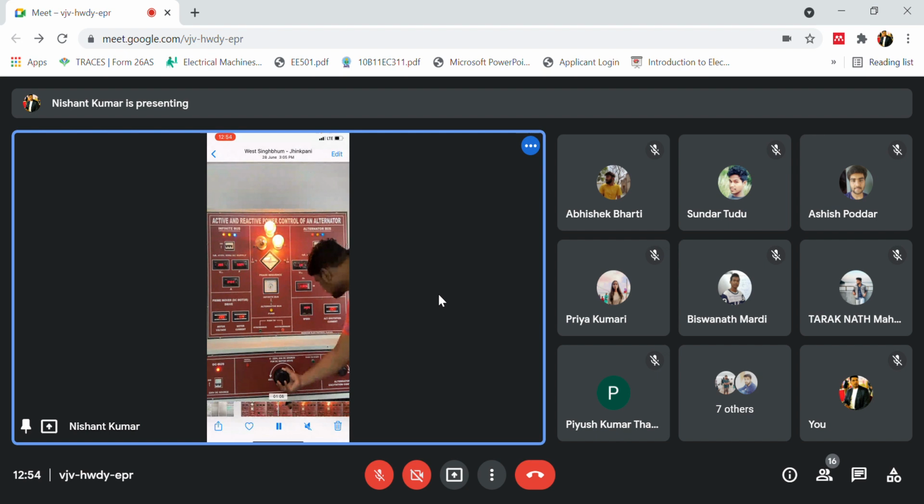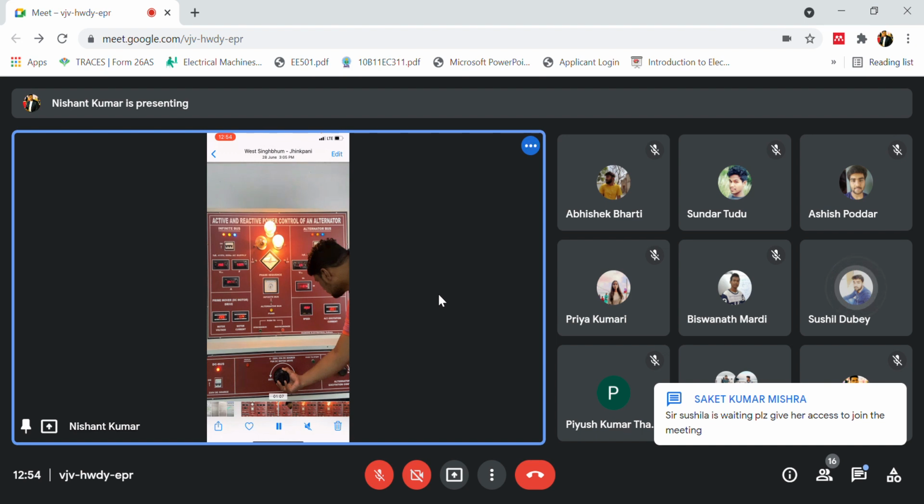Now, what I have done is I have fixed this at 1500 RPM. Your DC motor, or you could consider it a prime mover, is rotating at 1500 RPM. Now you could check all the ratings provided. Your motor voltage is 205, your motor current is 1.18, your speed you could see over there, and your excitation is almost zero.